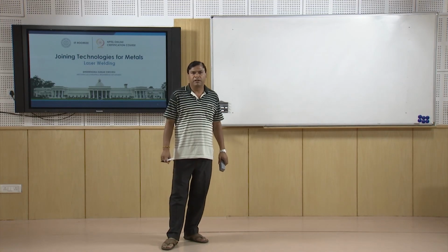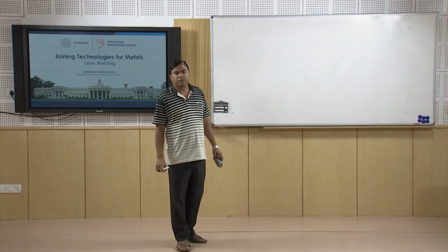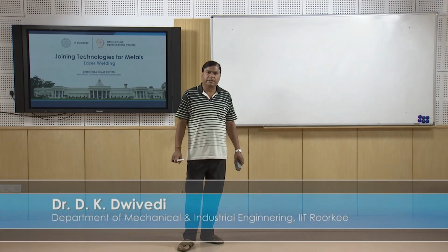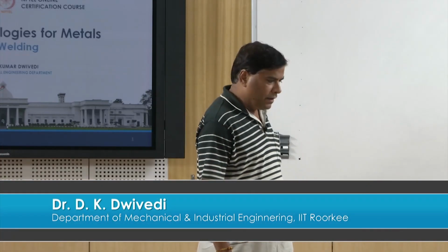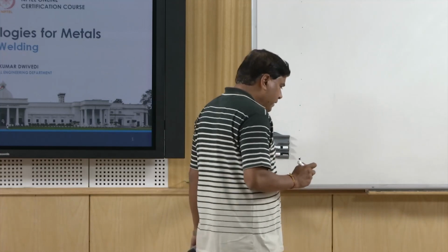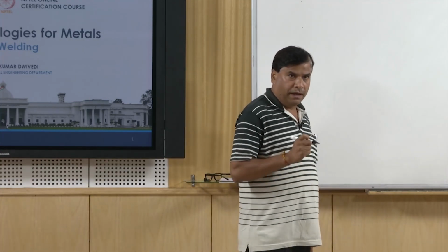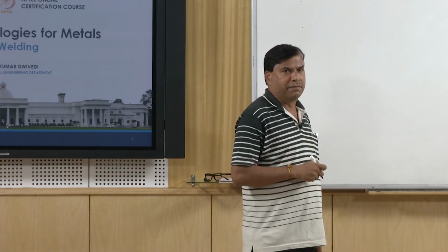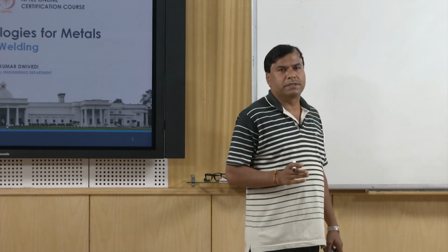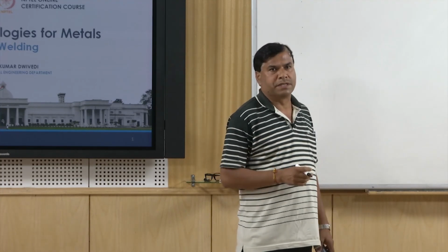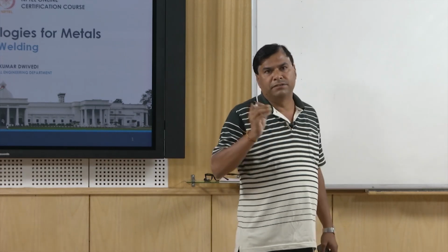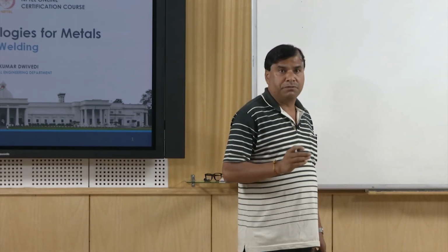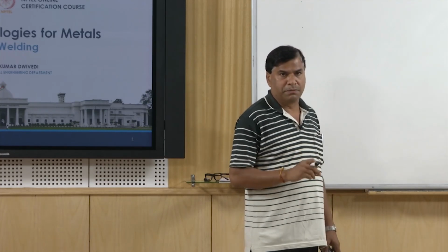Hello, I welcome you all to this presentation on laser welding, related to the subject joining technologies for metals. This is one of the radiation based processes; another is electron beam welding. Both these processes are known to offer higher power density, wherein right from heating to melting and evaporation can be achieved by adjusting the power density suitably.